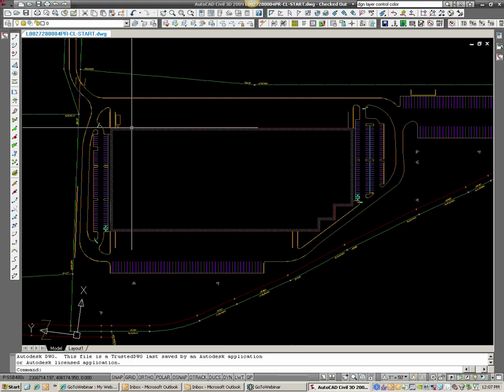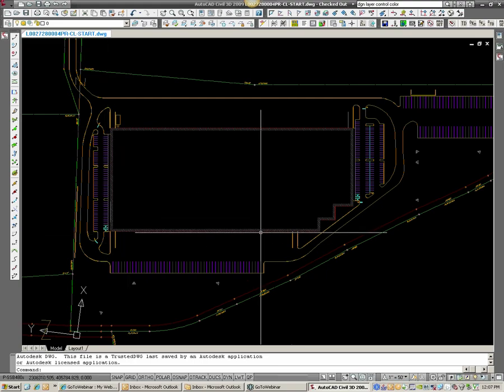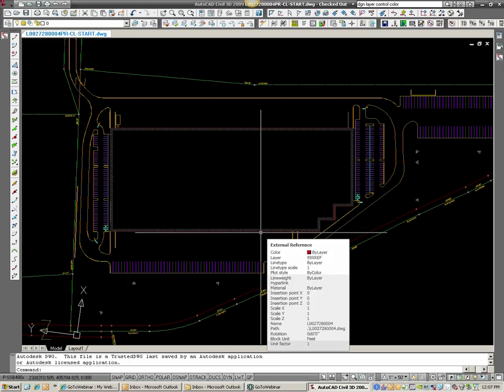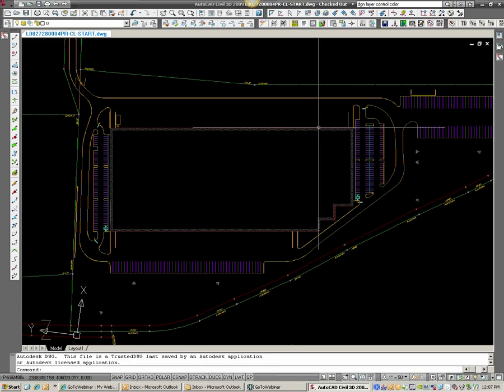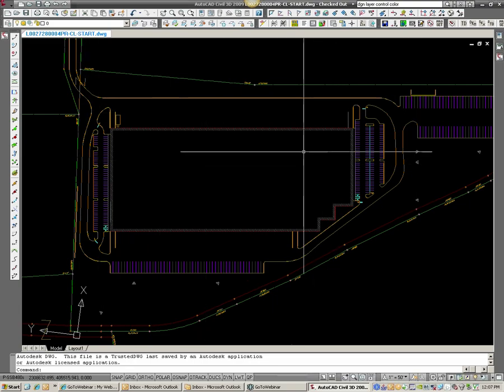So if you've graded by hand or in other situations and you're grading with the contours, it might seem a little backwards, but you've got to remember, if I take this building pad here, it really floats on the site. This is sort of one unit, right? I can move this up or down, back and forth, the whole thing at once, and since it's in AutoCAD or Civil 3D, you can grab the whole thing and slide it up or down, back and forth, or raise and lower.